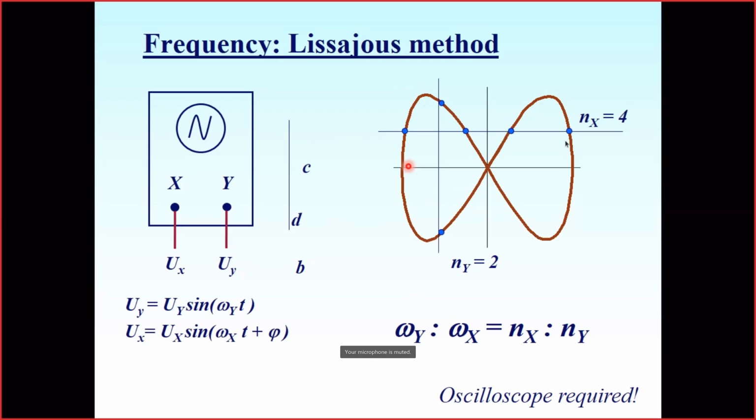No, it's quite clear what it means. It means that while in the x direction our signal changes from 0 to maximum, back to 0, then to minimum and back to 0, for this time the y signal has time to change to maximum, then to 0, then to minimum, one more to 0, one more to maximum, one more to 0, to minimum, and to 0. So while the x signal has 1 oscillation, for the same time y has 2 oscillations. And as a result, we see such a nice figure.